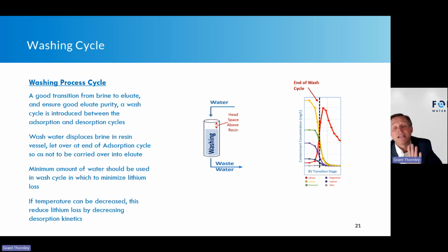So if that is an option, that you can decrease the temperature of your wash water, that will help in minimizing lithium loss. And again, we want to maximize lithium recovery and minimize lithium loss. And that is the wash cycle.